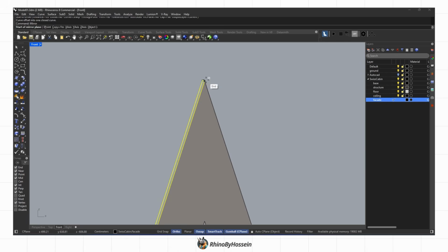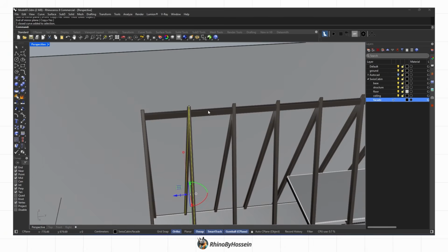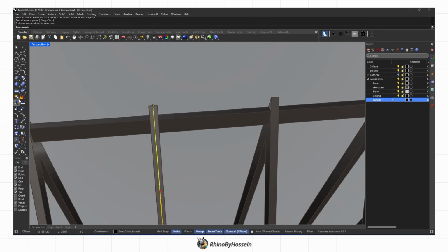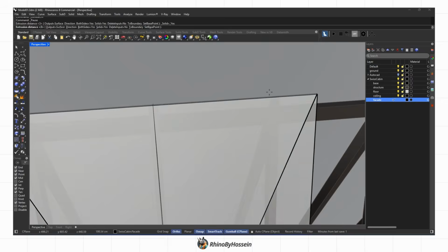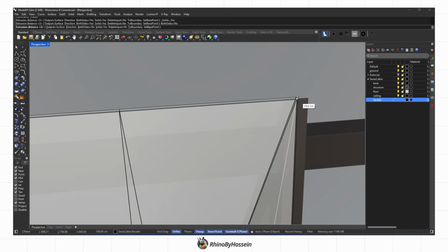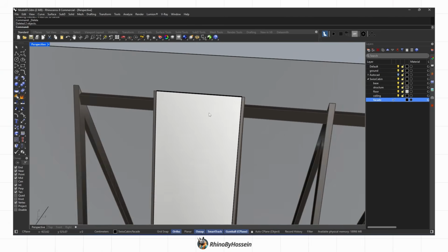To cover both sides of the facade properly, we mirror this profile along the center axis to create sheets for both sides of the facade. Next, we extrude these profiles to the center of the next beam. As you can see, the profiles align perfectly with the beams, ensuring there are no issues with dimension coordination.